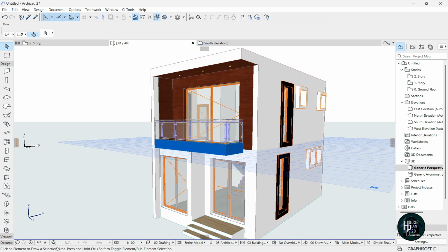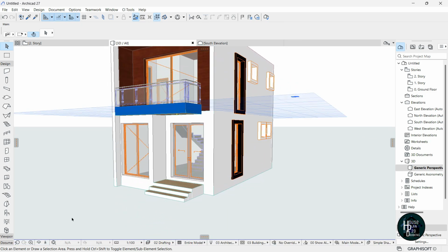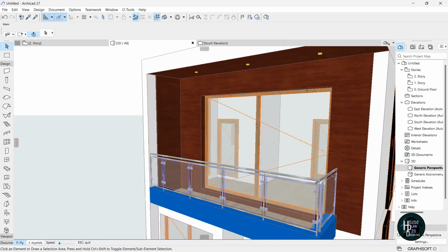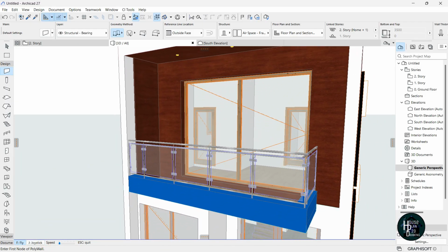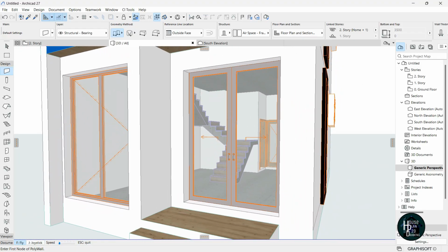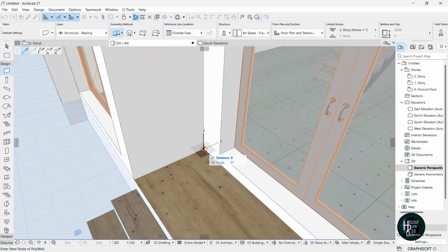So you're going to be having a design being shown like that. Okay, now we're going to do the same thing for this other side too. I'm just going to hold on Alt, select on this wall. Okay, now I'm just going to come down here. That's for me to come down, pressing down C on my keyboard. So I'm going to click this side here, straight to this side and double click.